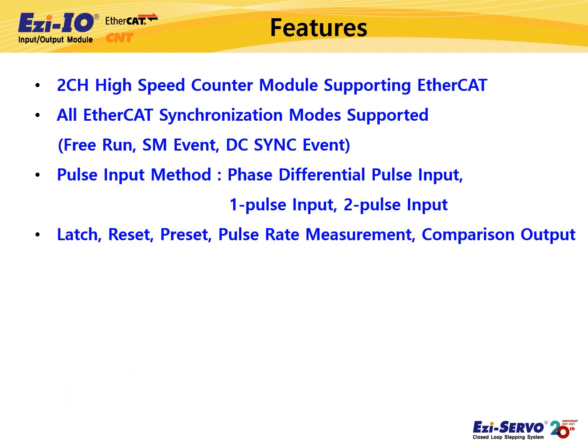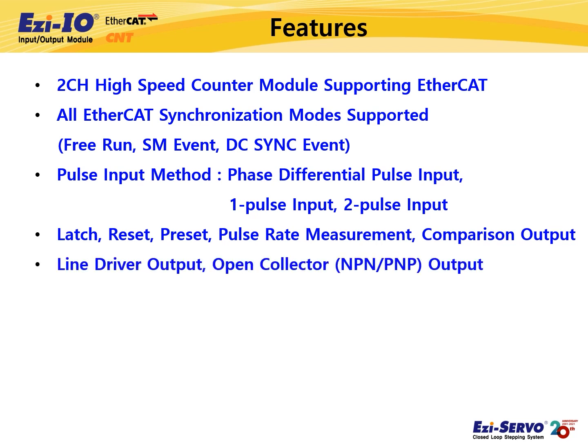Next, Ezi-IO EtherCAT CNT can be connected to various external devices without special input setting because the counter input circuit of Ezi-IO EtherCAT CNT supports both line driver output and NPN-PNP type of open collector output.